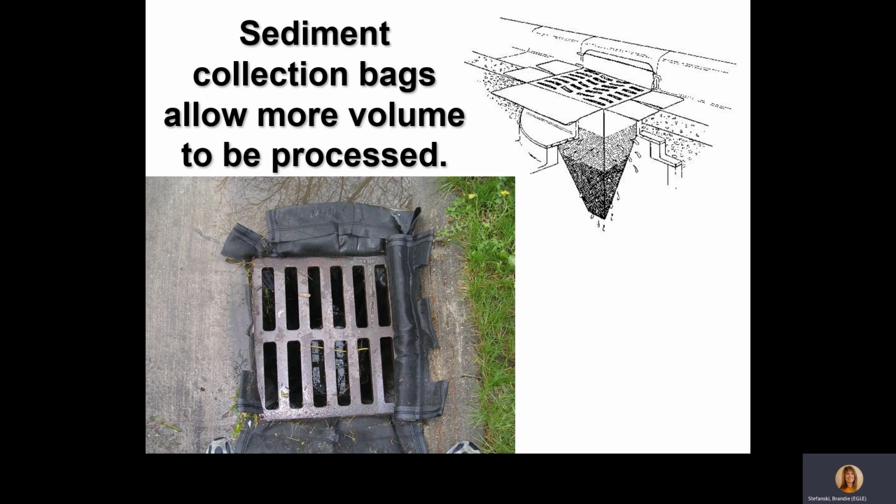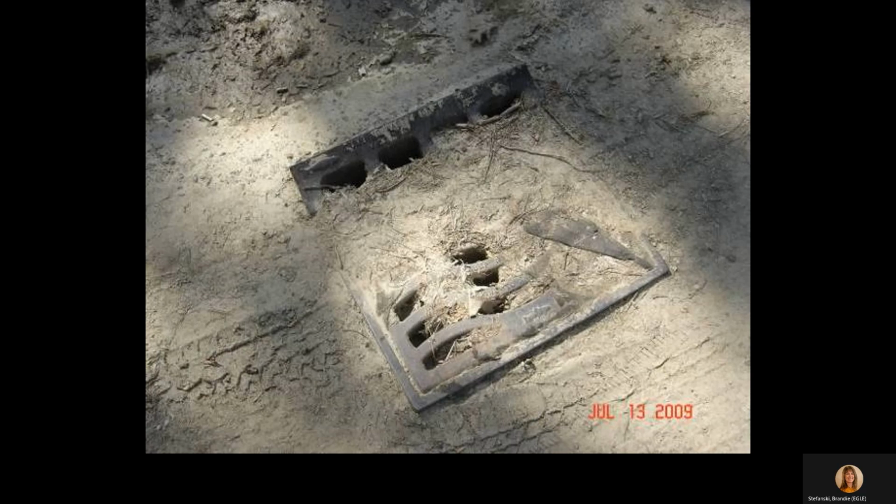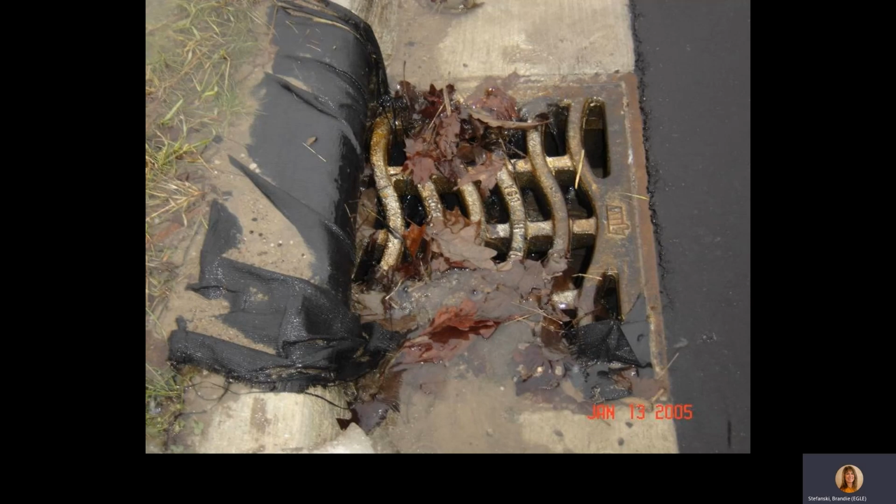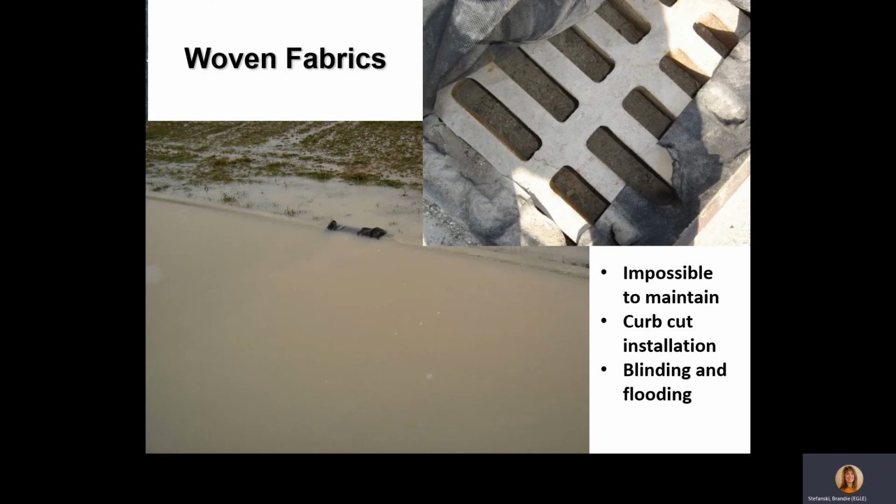However, if the wrap were over the grate rather than underneath, you could at least remove the sediment without dropping it into the inlet. The inlet protection requires maintenance in this photo. It is important to not rely solely on inlet protection for your site. Phasing and staging can reduce erosion from occurring and therefore reduce sedimentation and the need for maintenance. Ensure that there is a plan in place to remove the inlet protection so that the material does not fall in when the grate is lifted.